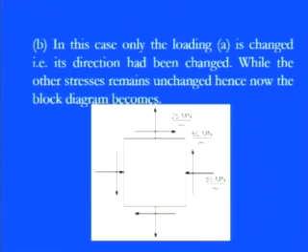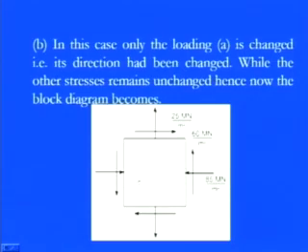the loading of part A, as in the x direction, earlier we had taken the 85 meganewton per meter square in the tensile part. So now in this part, you can see that it's a compressive one, because earlier it was tensile, so compressive stresses are there. So you can see here 85 meganewton per meter square in the compressive way, and other stress components are pretty similar to part A.